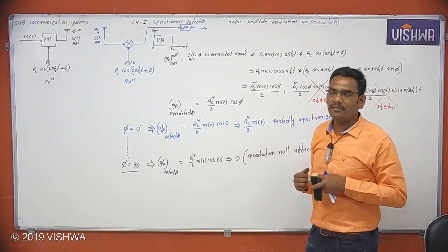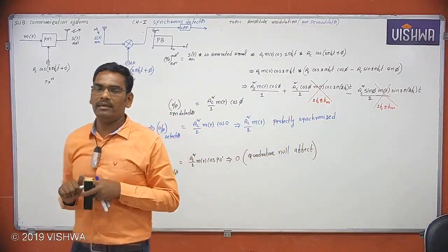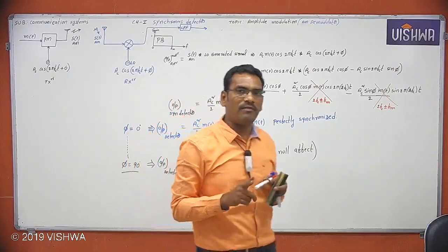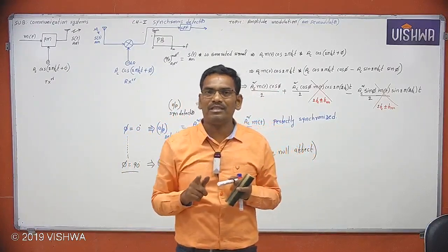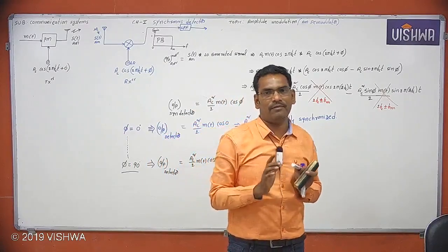That is the reason why the synchronous detector is not at all a preferable method. Where an AM modulation technique is involved, the demodulation at the receiver is definitely done successfully by the envelope detector itself.